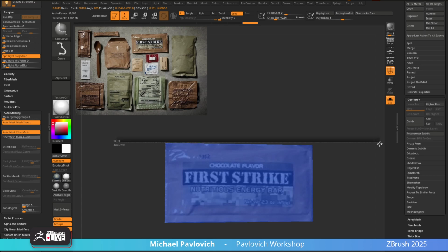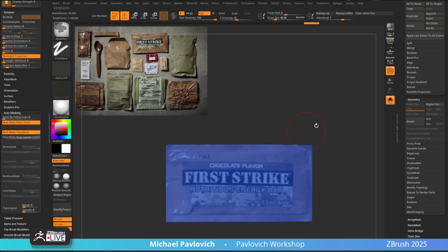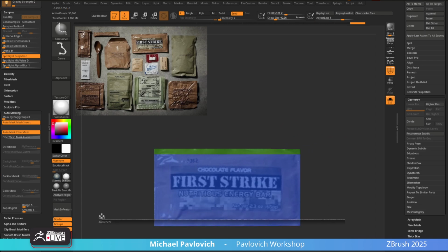And if you want to clean this up a little bit, just hold down Control Shift, and you can go through here and make this a little more regular. Control Shift Tab, Geometry, Modify Topology, delete hidden. And then again, here is where it's kind of stamped flat, and then here is where it's also kind of stamped flat.